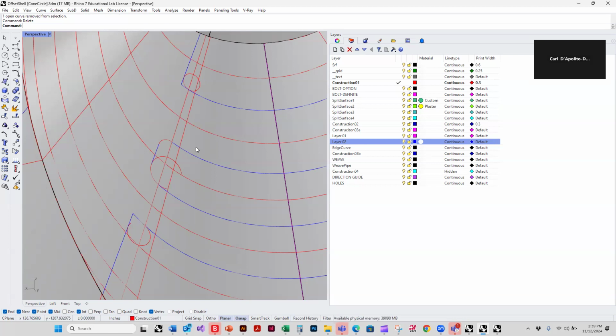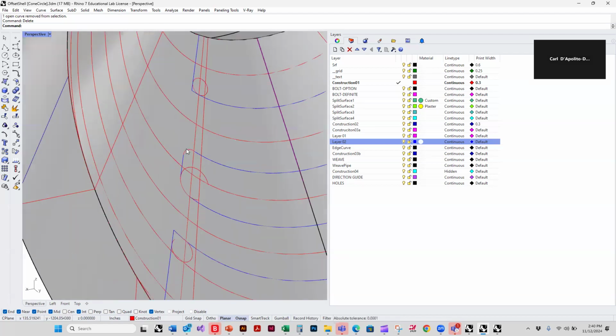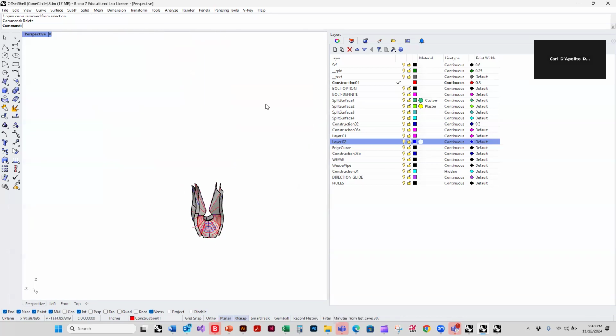Like if you're using the Zund with a knife, it can make a sharp corner, but the router has thickness, so it will go and it'll be rounded. If you want the two surfaces to hug each other, you need to put the roundedness in yourself. And then also you need to add tolerance.